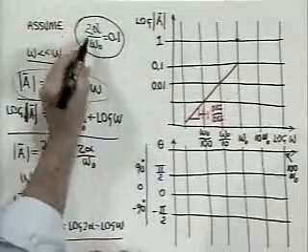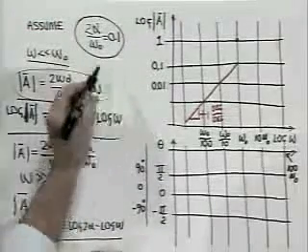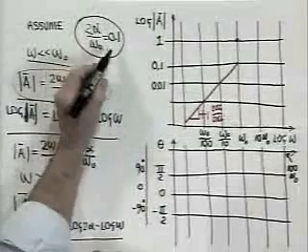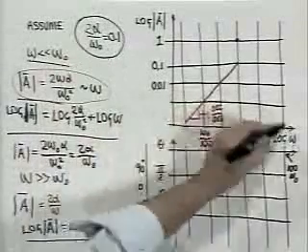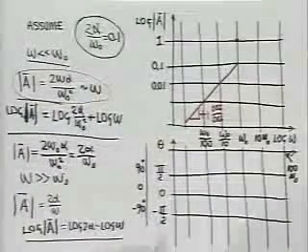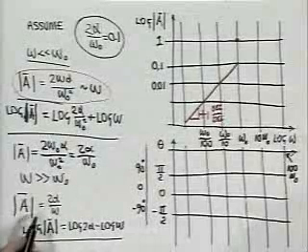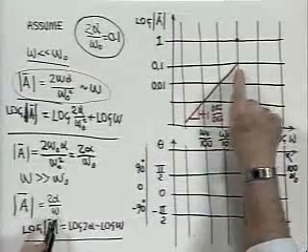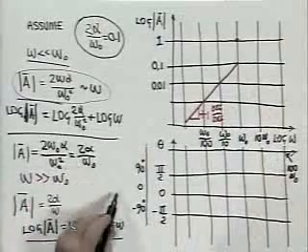If 2 alpha over omega naught is not less than 1, there is no resonance phenomenon. If it's bigger than 1, then there's just a smooth transition from the rising curve to the falling curve. But this asymptote, 2 alpha over omega, clearly passes through this same point, because if I let omega equal omega naught, I get 2 alpha over omega naught.